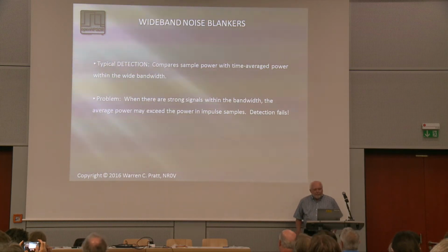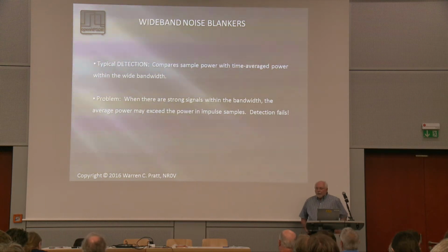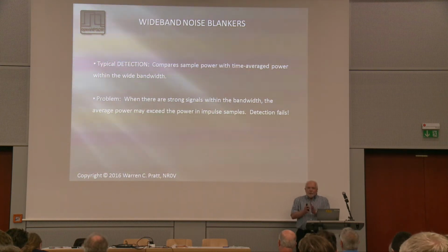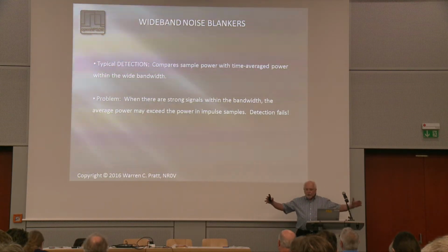Let's first talk about the wideband blankers. And there's some variations on this, but typically for detection in a wideband blanker, we look at the power encompassed in each sample, and we compare that power with the average power across some significant piece of bandwidth.